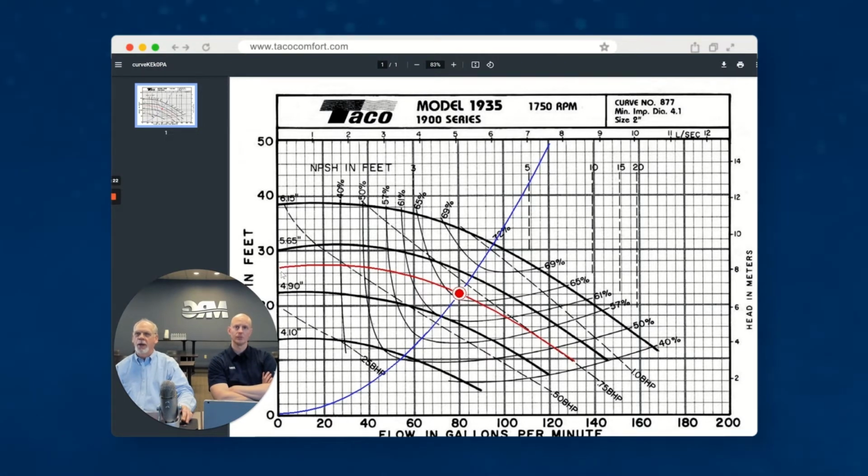I know that this red line here is a 5.35, and that's what it said on our selection. It gives us a dot here of where we are. On your pump curves, when you use this program, this pump is only going to operate along this red line. If you're at a constant speed, depending on your head, you will either go to the right if your head is less, giving you more GPM, or if you have more head against it, it will be less GPM. This is the pump we usually use on our boilers, John.